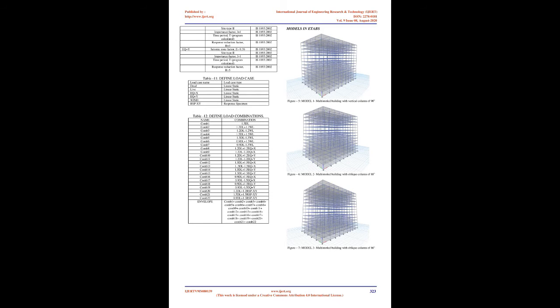Approach. 1. Adoption of several models of RC high-rise buildings consisting of 13 stories and for 3 types of structural systems in resisting lateral forces. The design models adopt walls of the central core of the stairs and lifts as essential shear walls to resist shear forces in addition to surrounding shear walls in both directions. The thicknesses of slabs and cross-section dimensions of reinforced concrete elements are identified, and after the process of analysis and design using the technical analysis design cycle for the imposed design models, make sure to achieve the Indian code conditions in structures designed to resist earthquakes regarding dimensions and ratio of reinforcement for each structural element.